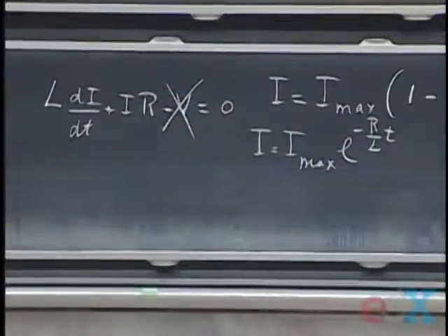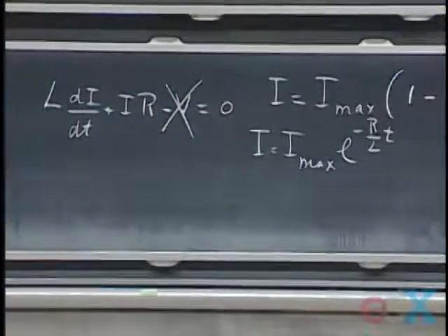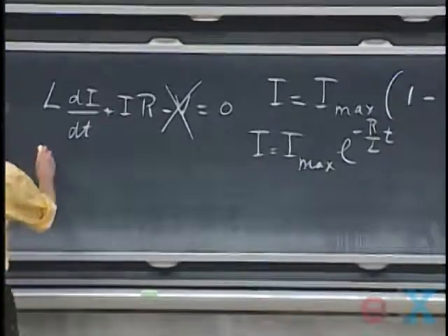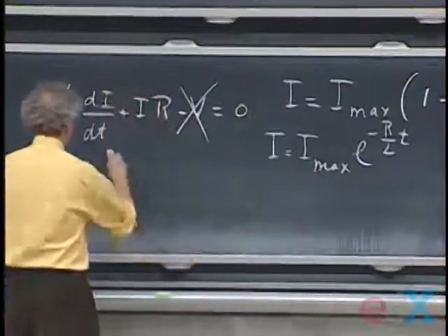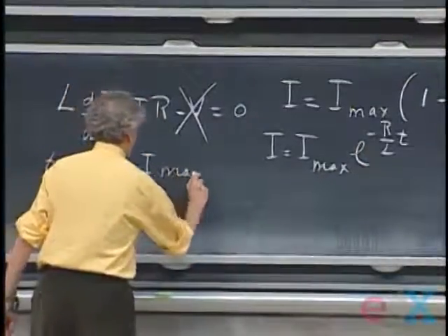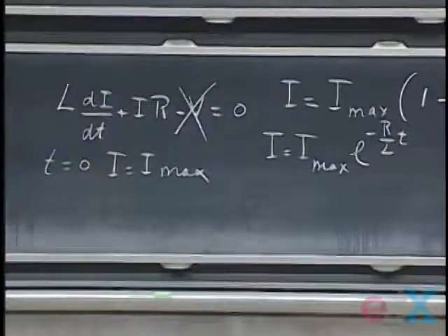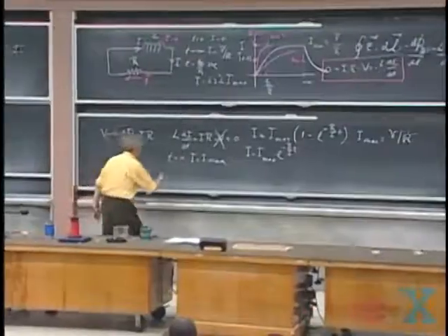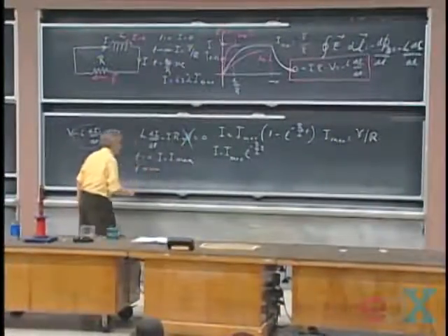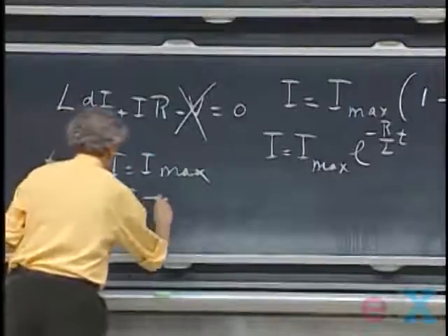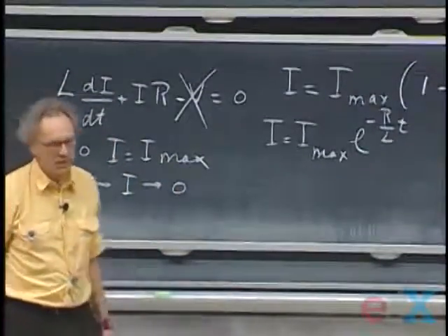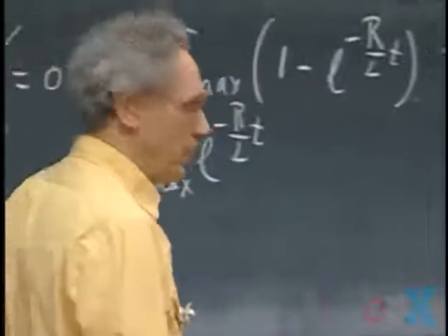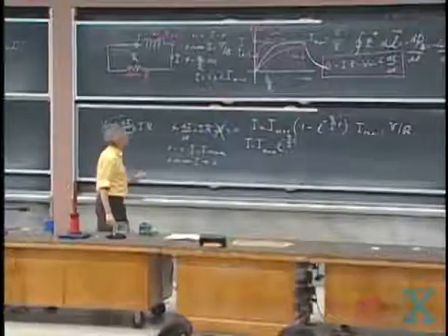And that exactly has all the quantities that you want it to have. Because notice that at t equals 0, when you put in t equals 0, the current is indeed maximum. And that's what you require. That's the moment that you make that capital V 0, the current was still running. But notice that when t goes to infinity, you wait long enough, the current indeed goes to 0. And if you wait L over R seconds, then you are down to about 37% of your maximum current.